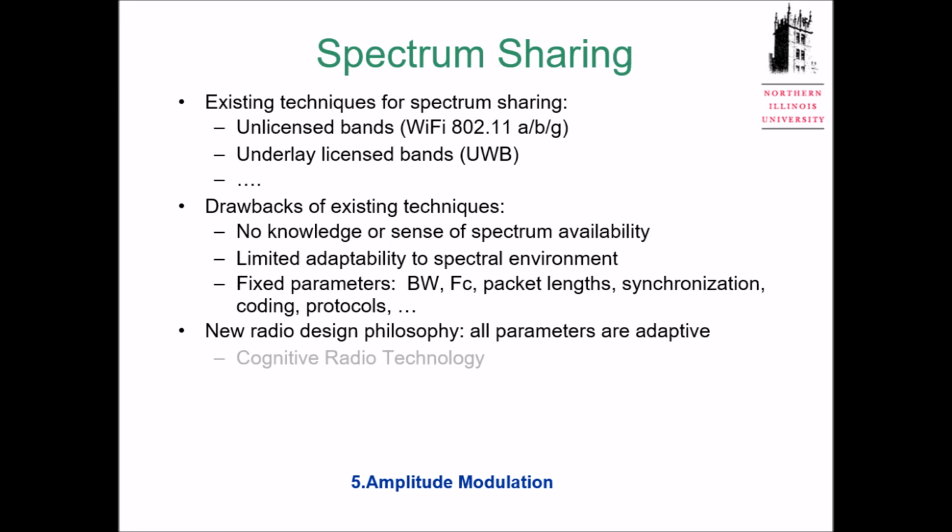We want to improve it. Previously we had double sideband large carrier. The next method we are going to discuss will still be double sideband, but with suppressed carrier. We are not going to transmit the carrier anymore, and with this method we are going to improve the efficiency. However, there are always cons and pros: your receiver will be way more complicated. So we're going to leave it to the next lecture.